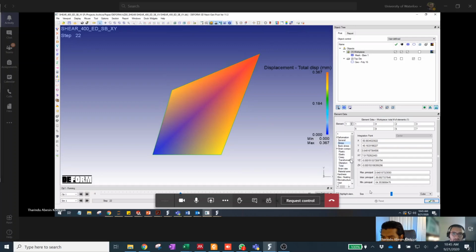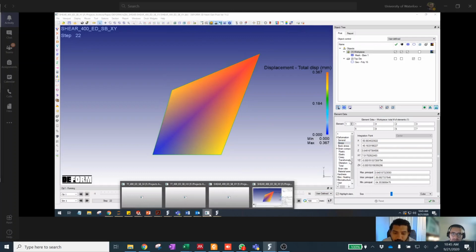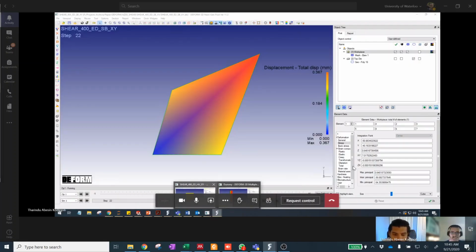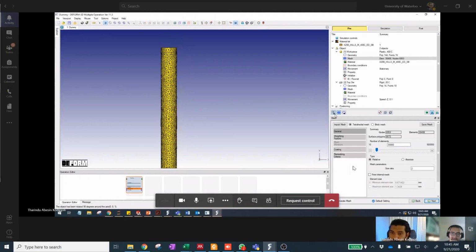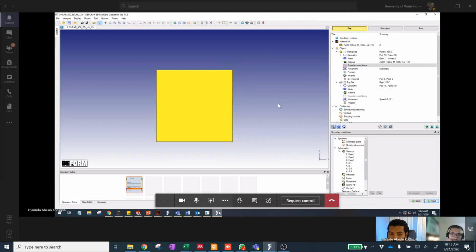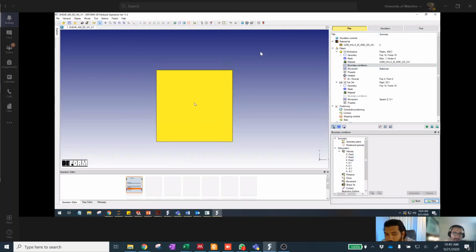Go to your boundary conditions. I think that's probably the next step you were going to do. So for the boundary conditions, I'll have to go to this thing here. Hold on. It looks like it's imposing a Y boundary condition on one of the nodes, and the other node is not. It's pulling diagonally on one node, and the other one is just moving laterally.